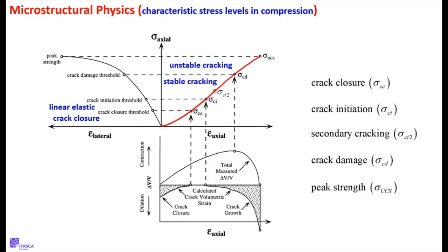Experimentally, it also has to be properly done when you do this numerically, which means that to calibrate, we're going to do synthetic tests. We're going to model the same test, and we're going to apply platen velocity, and we need to make sure that it's slow enough that we get the same answer each time. And so that's a very important thing.